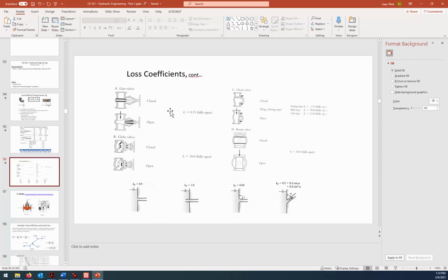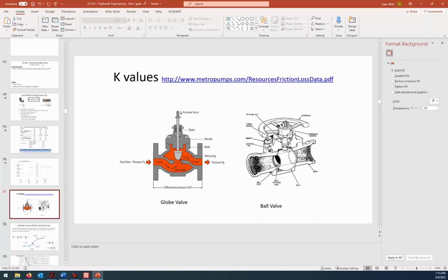So the valve that goes into my house is a gate valve, but then underneath my sink, I was telling you earlier about the water purifier that I've got. So I have a ball valve going from the water line to my sink. The little branch line to the purifier is a ball valve, and I guess the reason they selected that is so that you could cut it off really quickly. Just with a quarter turn, you can close the ball valve.